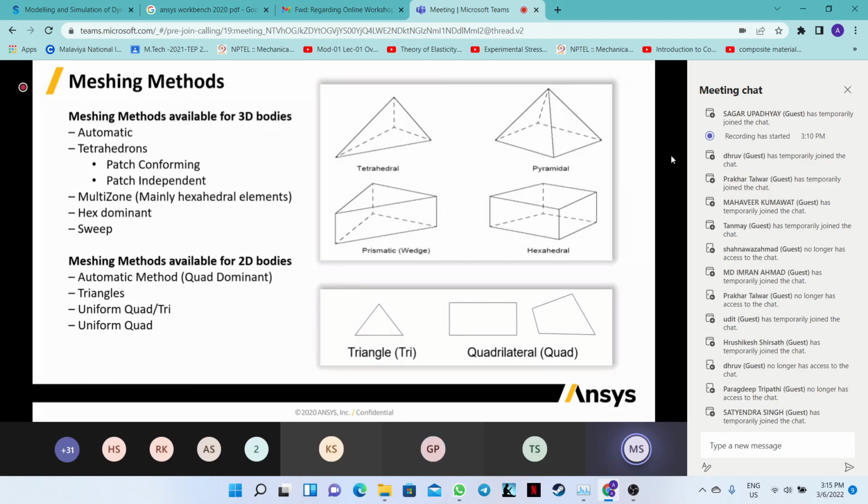When you have sharp edges, you can switch to patch conforming, because these are the best suited methods. Out of that, we look at the surface, how smooth it is or how intricate it is. Depending on that, we have to try both methods and implement it.